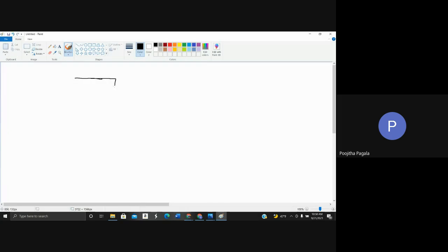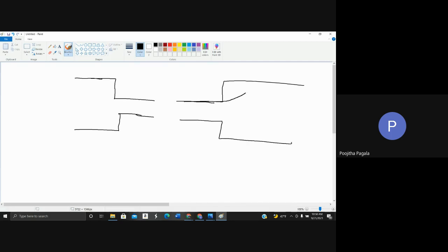So I'll show you both the cases comparatively. This is a contraction, and then you have the second case, which is an expansion. When you have an expansion, the fluid straight away expands. And this region has backflow. Vortices are formed in this region.